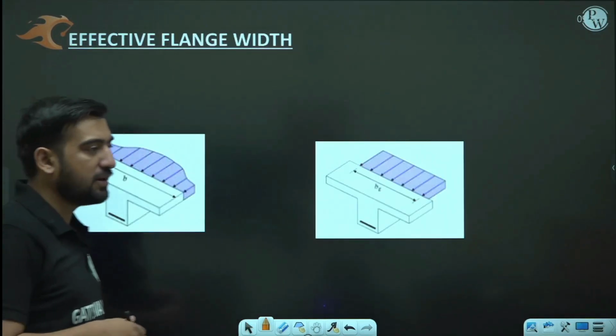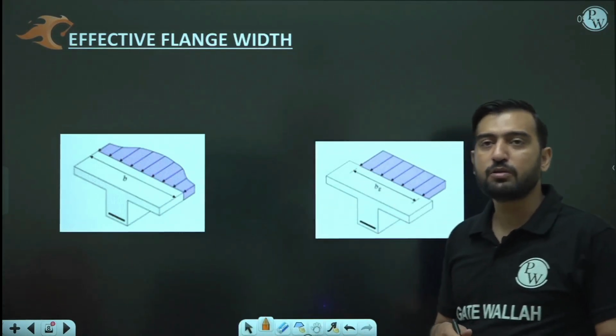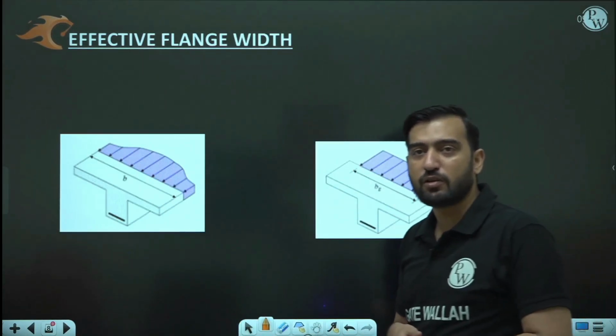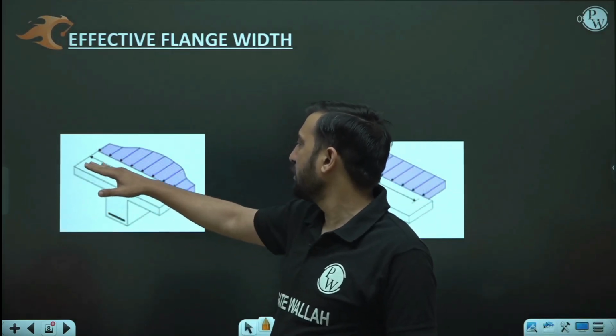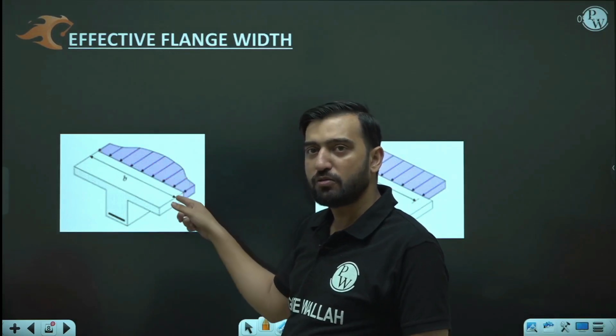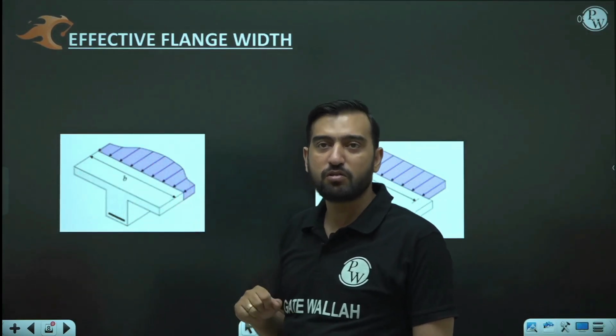Next, my dear friends, very important: how to calculate the effective width of the flange. My dear friends, if this is my flange and you are seeing the stress distribution here, you can see that over the entire width of the flange, the stress distribution is not uniform.